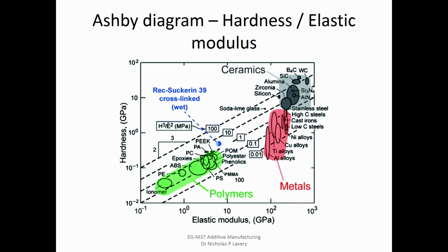Often we see very low elongation for the parts, and you get a lot of anisotropy and things like that, which I'm going to show you about in some of the results that I've got on here. But they were saying that if you choose the laser properties correctly, you can get super high elongation with very, very high yield and upper tensile strength by literally combining builds in the additive machine, by optimizing the lasers and using a lot of computer modeling and tensile tests to match them all together. And literally right from down almost up to the nanoscale, they're actually engineering the microstructure. And it's a hierarchical thing which actually allows it to have the super elongation. So there's some very interesting properties that you can get. But there's always these trade-offs.